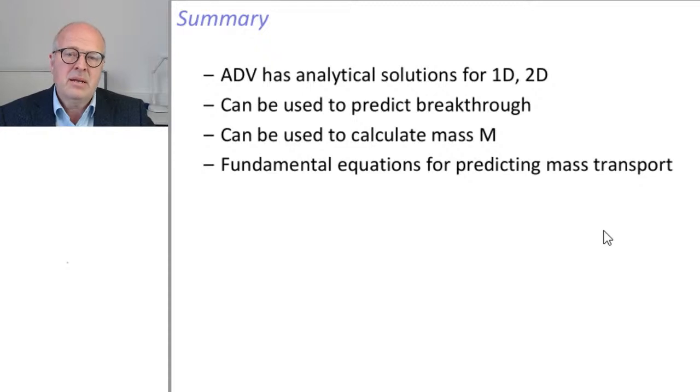This will be the crucial tool for you to identify the right amount of tracer used for your trace experiment, because you want to be below a certain maximum concentration, which is the visibility, and you want to be above your detection limit. So I always try to be a factor of 10 below visibility at my detection point and a factor of 10 above detection, rather a factor of 100.